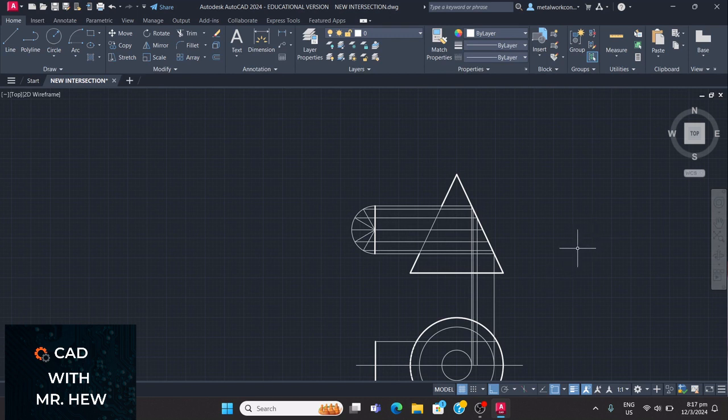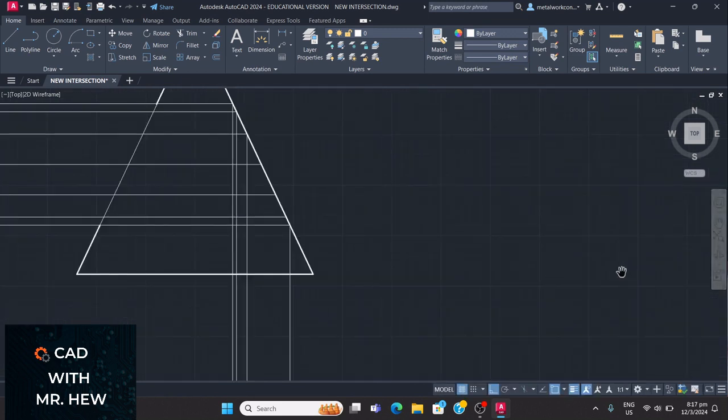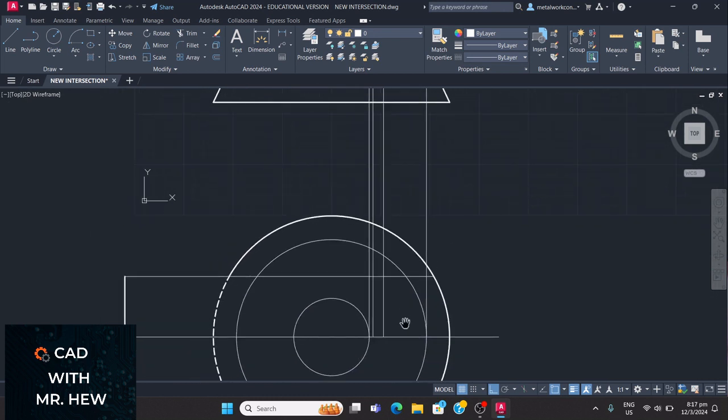Right? How you know if it is straight? Yeah, I'm gonna show you how you know if the line is perpendicular. So let me show you. There, I'm gonna blow it up for you. So look, when you're coming down, the object snap. You see that little green right angle symbols? Look at it there. Look, I'm gonna come down. Right, that tells you that the line that you're coming down with is perpendicular, and that's the object snap perpendicular. All right, I can show you how you turn it on and off in a little while if you wish to. All right, so we press enter.